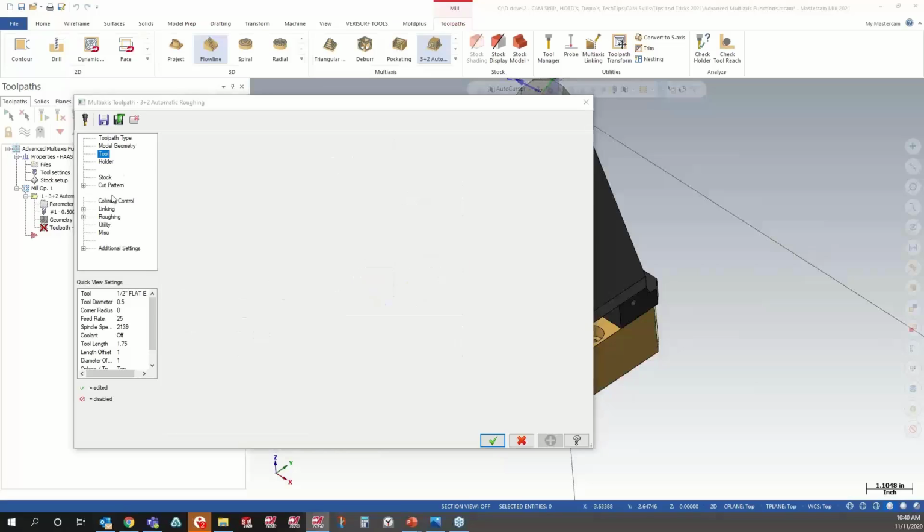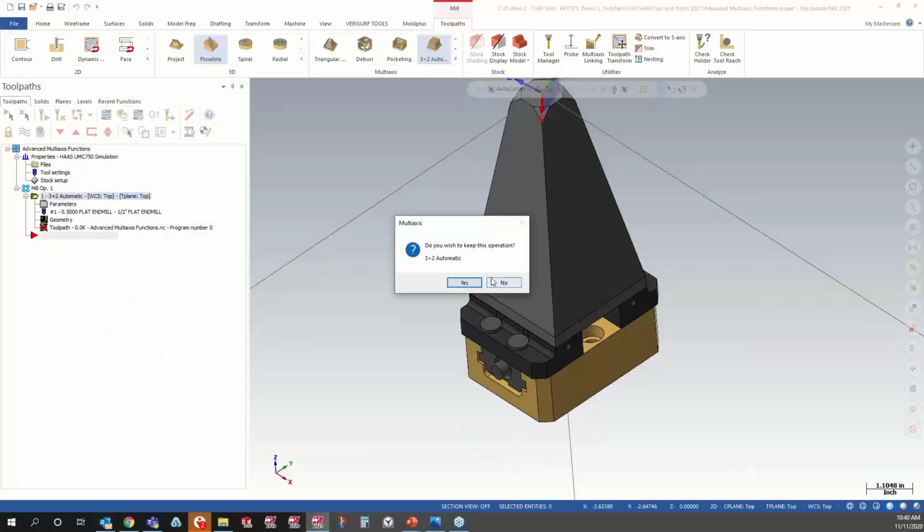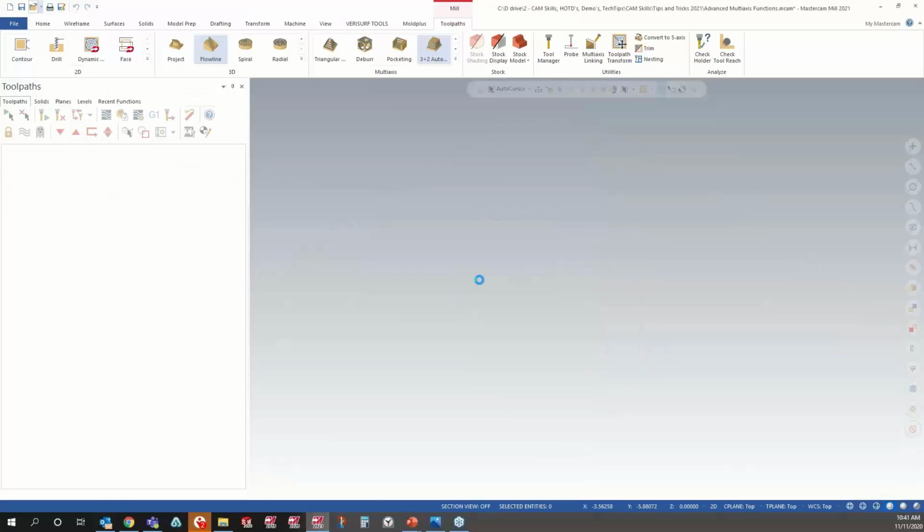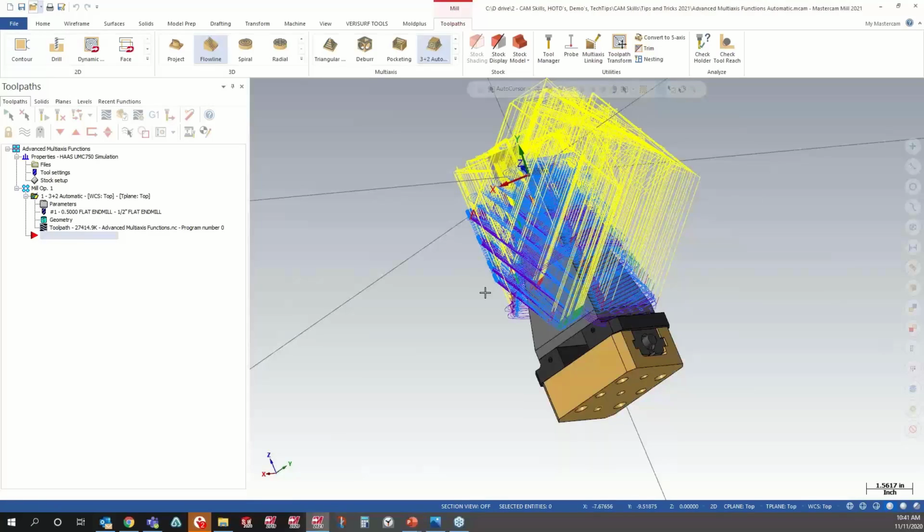We're just going to hop down to the tool axis control. Now, if I left it at automatic and said you can move as much as 90 degrees and search every 10 degrees, it's going to try to find as many flats as it can to rough out with these parameters and get something that looks sort of like this.